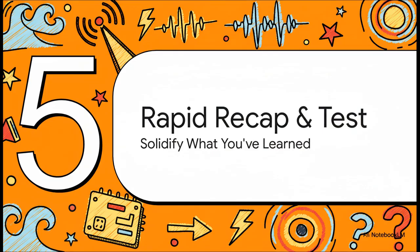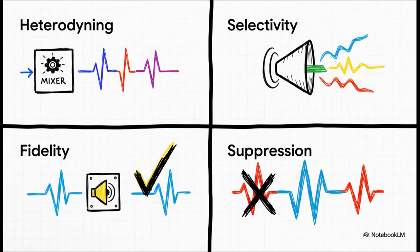So before we wrap this up, let's do a super fast recap and then a quick quiz just to make sure all these new ideas are locked in your brain. All right, lightning round. Let's hit these key terms. First, heterodyning. Remember, that's just mixing two signals to create a new one. Next up, selectivity. That's how good your receiver is at picking out the one station you want and ignoring everything else. Then there's fidelity. That's all about how accurately the receiver can reproduce the original sound. And finally, suppression. That's the trick SSB uses to get rid of the parts of the signal it doesn't need.